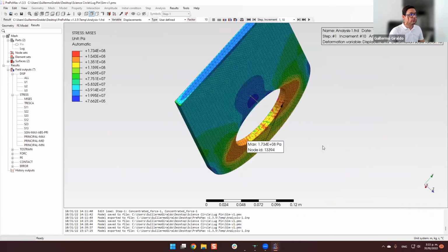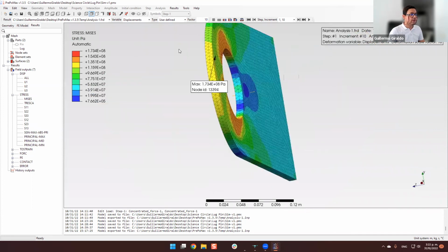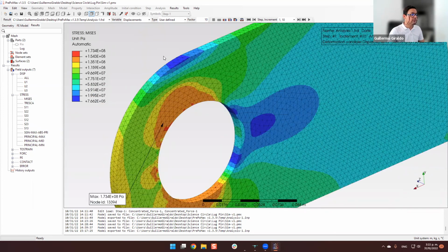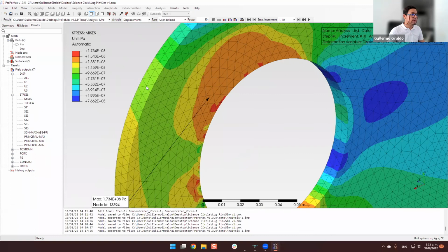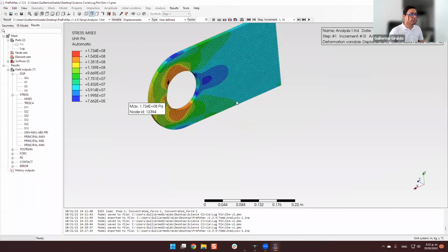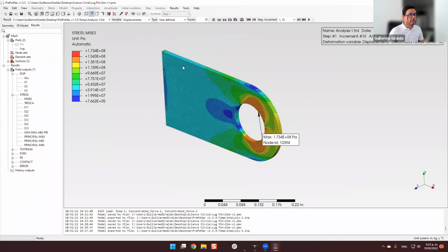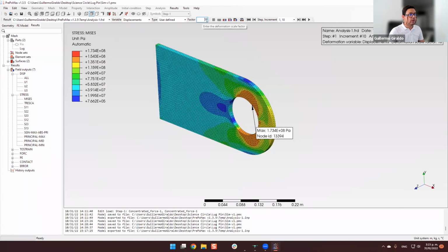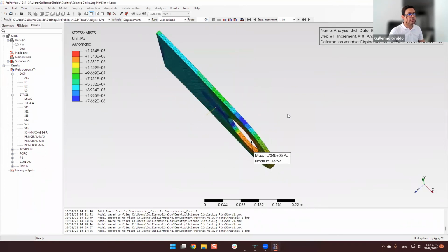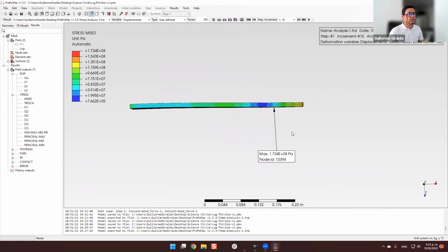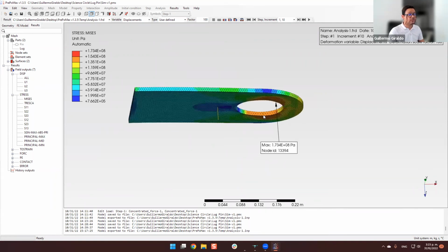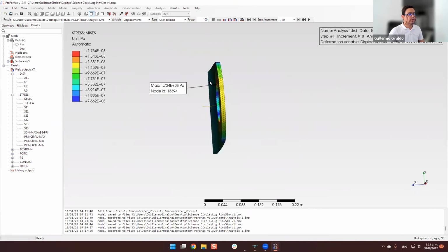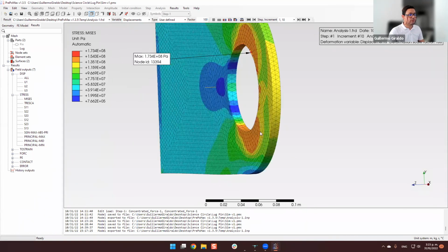Also, due to the mesh, I only have 2 elements, and it seems like there is a plane of elements, but it's not real. There is not really a plane of nodes here. This is what causes a little bit of deformation to the side. You can see that it is deforming a little bit. So you will need to perform your mesh independence analysis, just refine this mesh a lot to see if this lateral displacement is real, or what is causing it.